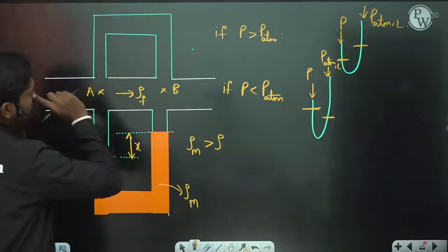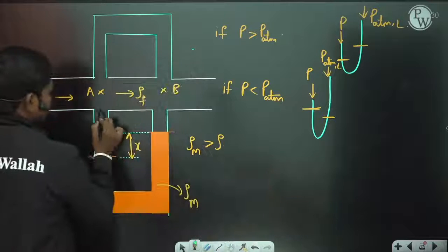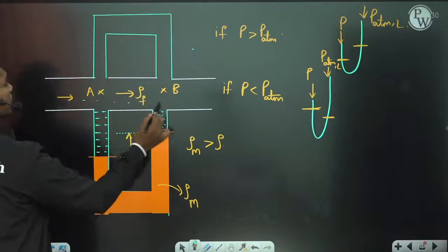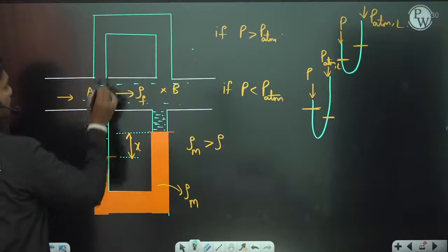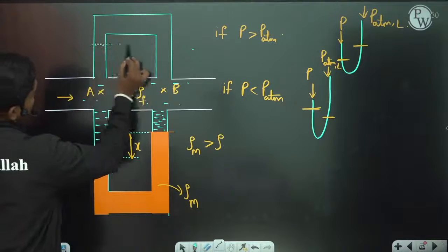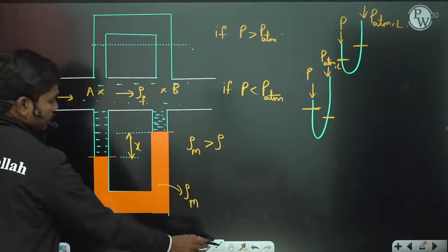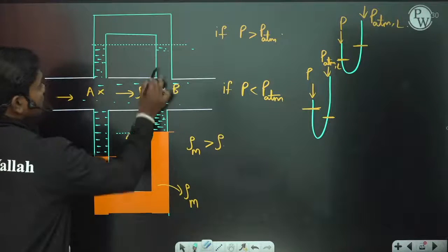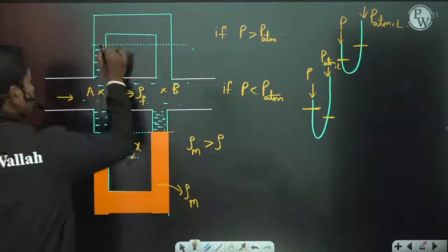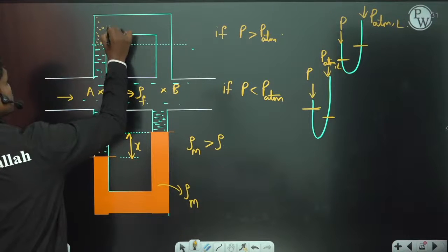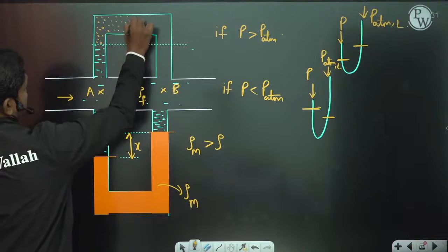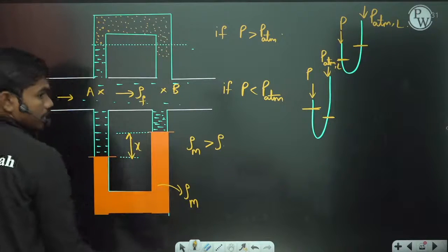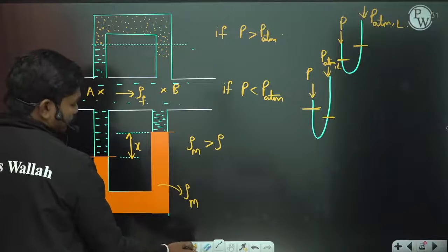Okay, now let us take the case of an inverted tube manometer. So here, this is water, for example, let us say water or air, anything is flowing. Similarly in the inverted tube, if PA is high, if you try to draw an interface like this, then definitely water is filled here. To some extent you have this gas. So you have some manometric fluid like this, so that you have this interface.